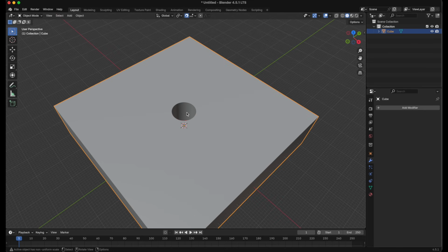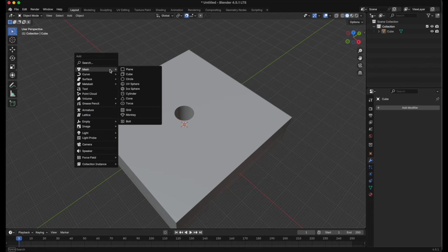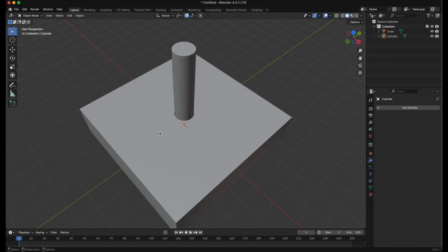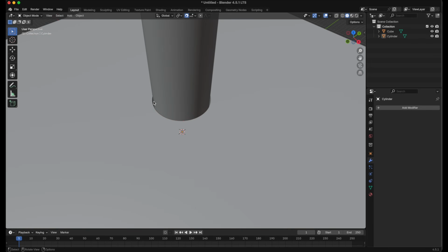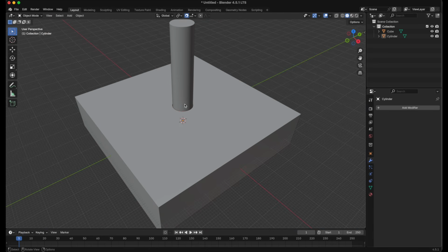Now, when I chose the dimensions for this hole here, I typed in 5.2, and that's because I wanted a 0.4 millimeter extra clearance. So for example, let's create another cylinder here. And this time, instead of 5.2, I'm going to type in 5, okay, and press enter. Now you'll notice it has a radius of 5 millimeters and a diameter of 10. So essentially, we have a 0.4 millimeter extra clearance here. And because we're printing this box in this orientation, it'll have a nice, smooth print. We don't have to worry about any layer lines at the top of the arch.